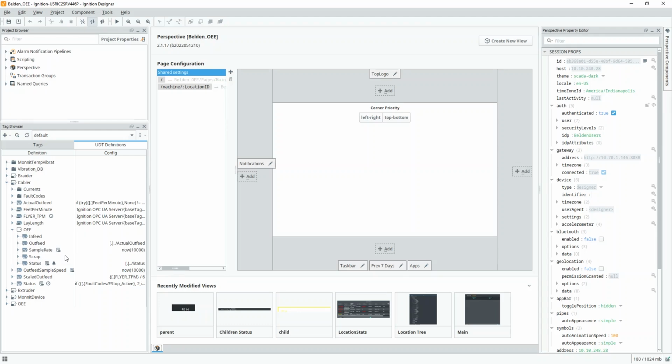Once the data made it into the OEE UDT, the associated tag change scripts allowed for forwarding of data to the data model in the SQL Server for SparkMES. And once there, a series of views and stored procedures provided a simple OEE data interface that could be used for reporting in both Ignition and external interfaces such as Tableau.